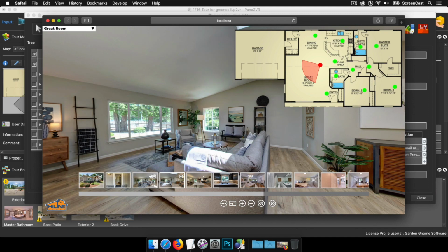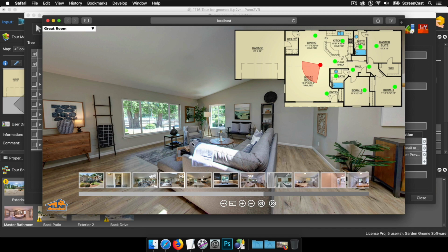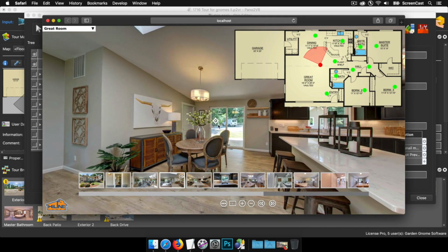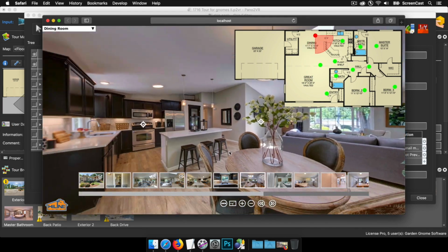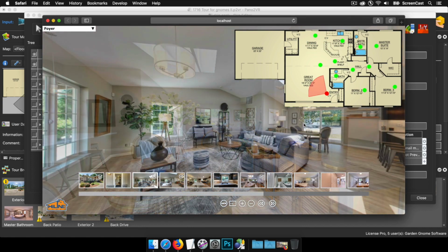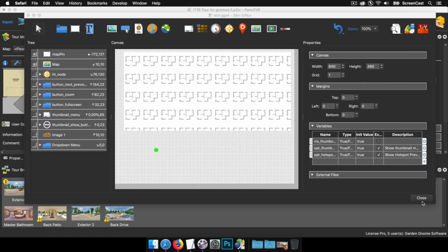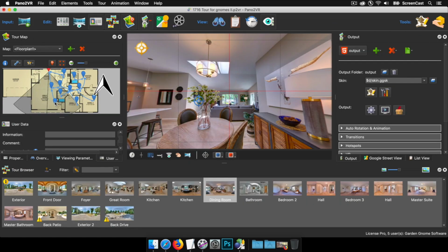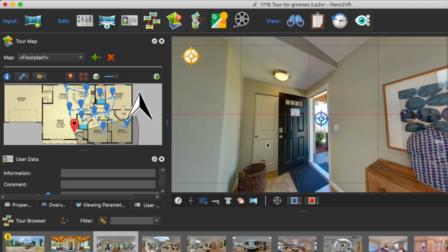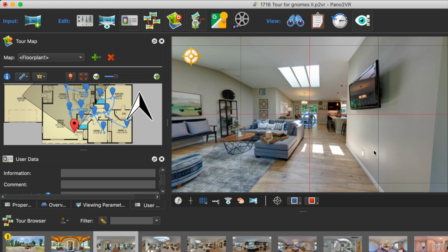Okay, one of the other things that the project is doing is opening up the panoramas, looking at various parts of the room. Now this is what obviously the realtor wanted, but for me what I'd like to do, and I want to show you how to do this, is that when I click a hotspot to still be facing the direction that we're going. Alright, so to do that in Pano2VR, it's quite simple. Just close the skin. I'm going to select the first node inside the floor plan, and how we're going to do this is a couple more keyboard shortcuts.